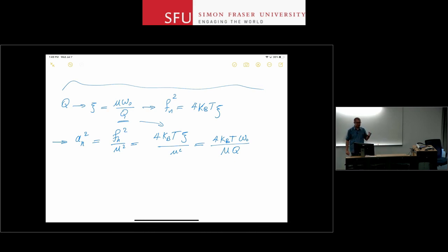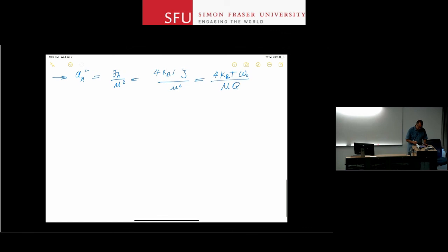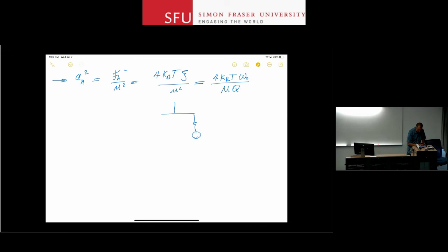Now the point here is, how much is this comparable to, let's say, the noise that I produce because of the resistors in my Wheatstone bridge and the amplifier. So if I look at those, what I have is, let's say, a Wheatstone bridge. Each one of those resistors has its own noise source, right? And then I'm measuring these with an amplifier. The amplifier itself has some noise.